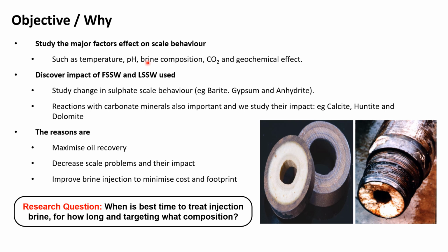Objective of my study: to study the major effects on scale behavior, for example temperature, pH, brine composition, CO2 availability in the system, and geochemical reaction. Discover the impact of full sulfate and low sulfate. Study the change in sulfate scale behavior, for example barite and gypsum. Reaction with carbonate minerals is also very important, for example calcite or dolomite.